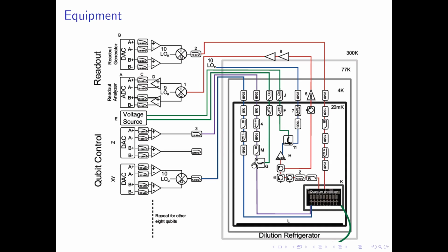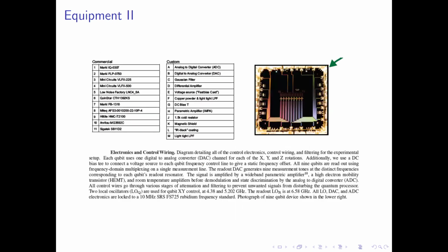And then you have various layers of temperature. You have 20 millikelvin over here, then you have 4 Kelvin, then 77 and 300. Then you have different types of equipment. That's the whole family of classical electronics that can be constructed. You can construct amplifiers based on Josephson junctions. They have very low noise, so you can amplify certain small signals with Josephson junctions. That's the whole art of doing so. Well, this art is not yet too much pronounced in Poland, unfortunately. So there is always a space to do something with that.